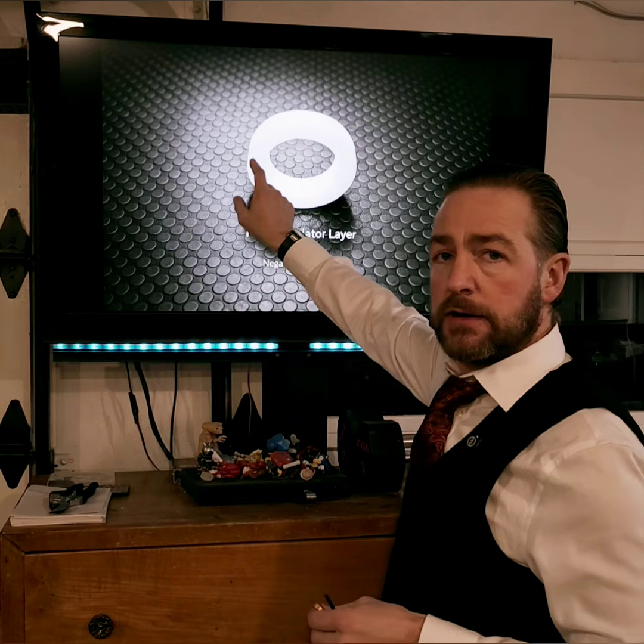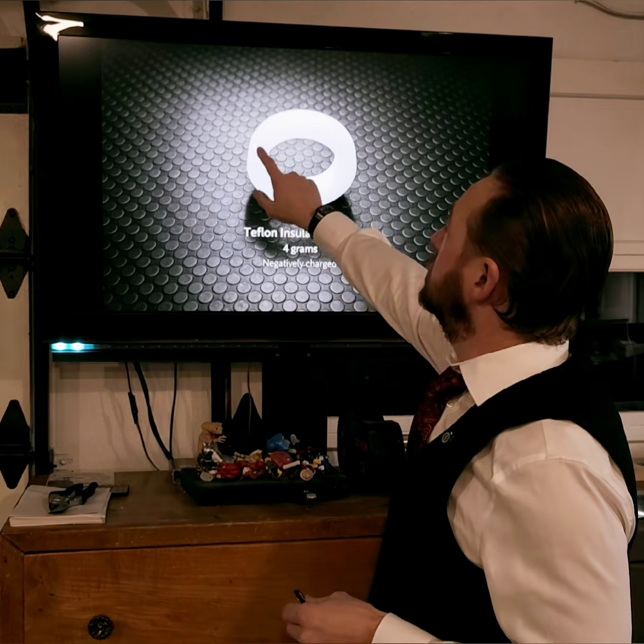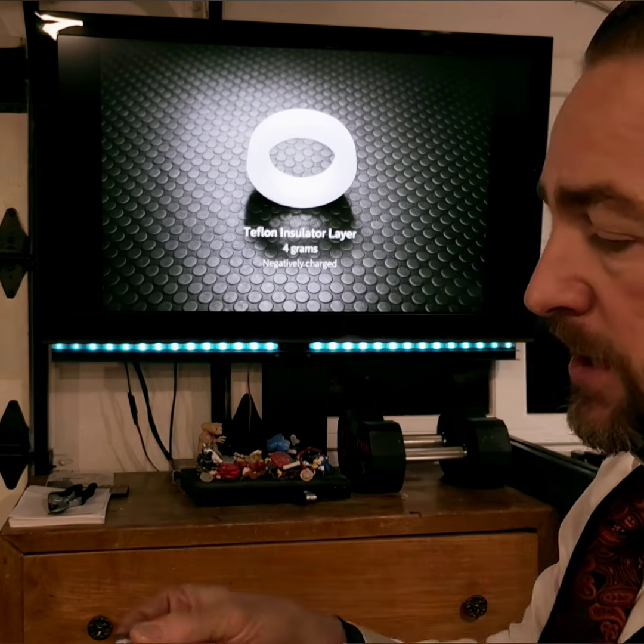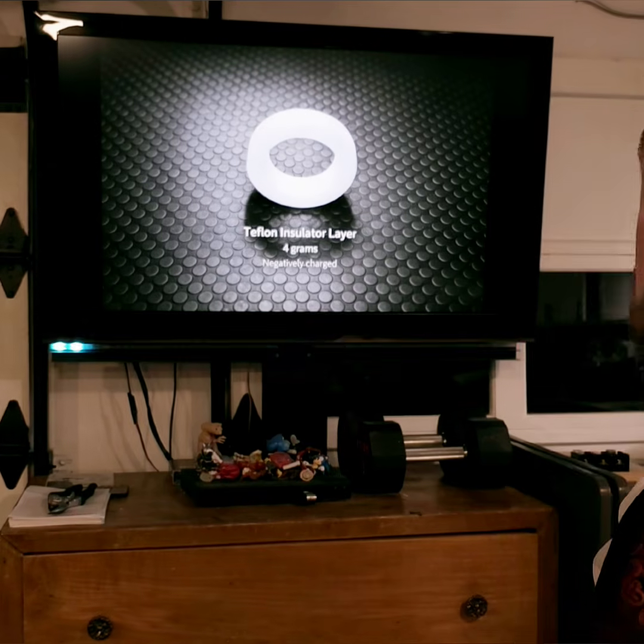One of the things I learned through doing much research with nylon 6 is that when you charge it negatively or charge it positively, the charge will soak through the entirety of the material. With Teflon here, the charge basically stays retained on just the surface of the material, not soaking deep into it. So nylon 6 has some interesting properties. The other thing I like about nylon 6, you can 3D print it. Teflon, forget about it. It ain't 3D printable. You just get the blocks or the rods and machine it out raw.